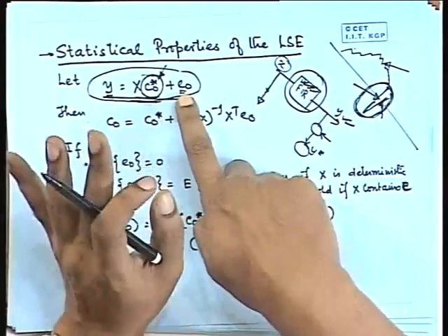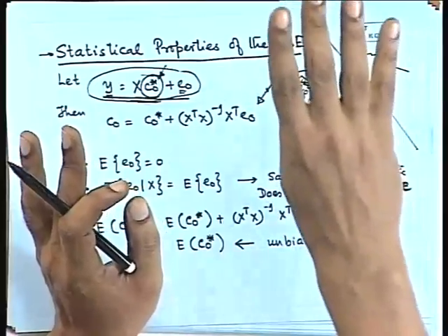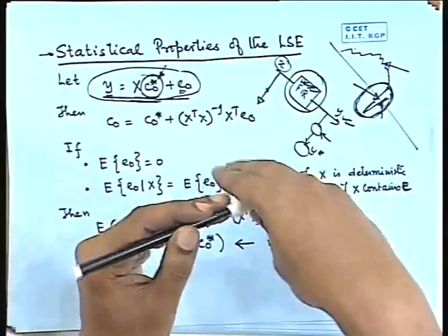It may or may not be the same. In general, it is not the same. The data may be generated, let us say, by a 10th order filter, and it is still valid to try to estimate a second order filter. Nothing wrong in that. But in this case, we are just synthetically assuming that a 10th order filter has been used to generate data, and we are estimating a 10th order filter. Then can I get back those parameters which were actually used in generating y?